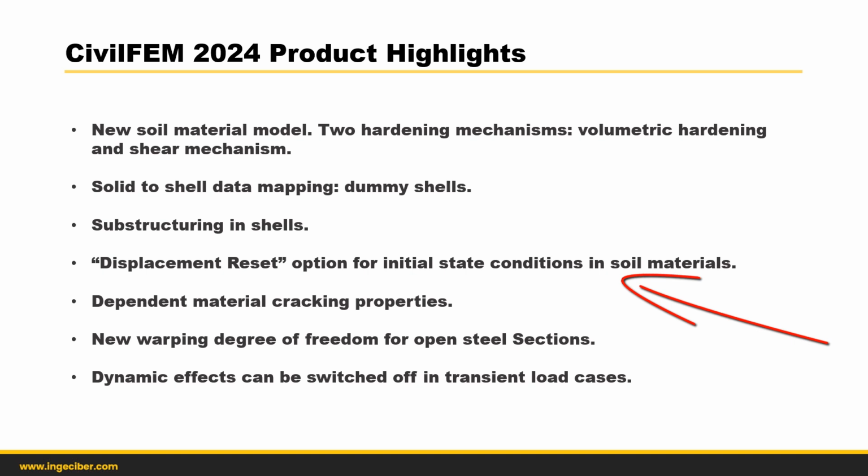A reset displacement option has been added to load cases. This option simplifies the creation of initial state conditions for soils without self-weight deformation, or for obtaining only relative strains and deformations from the desired moment of the simulation.